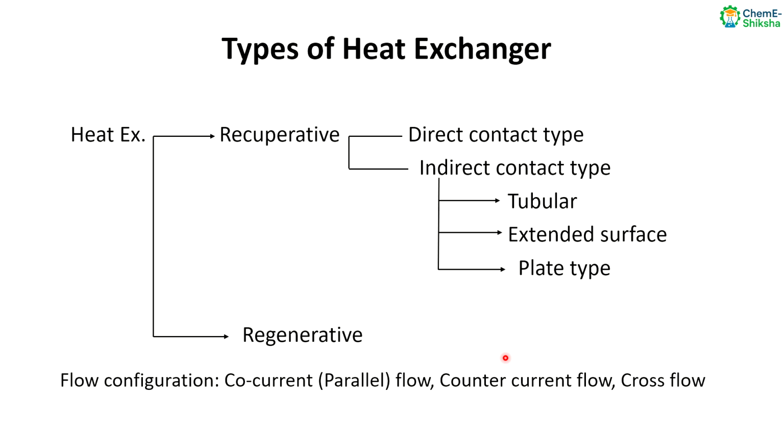I am again repeating. For a recuperative heat exchanger, there are separate flow paths for each of the fluids, which are exchanging the heat through the heat exchanging wall. And for a regenerative heat exchanger, the flow path of the two fluids is the same. The fluids will alternately flow in the same flow path and exchange the heat, and the heat will be stored in the medium before being transferred.